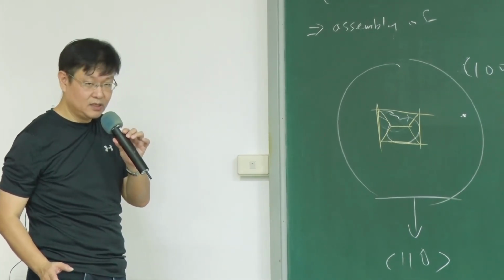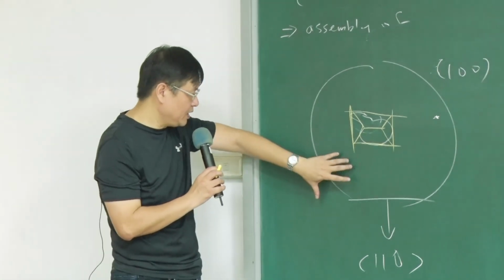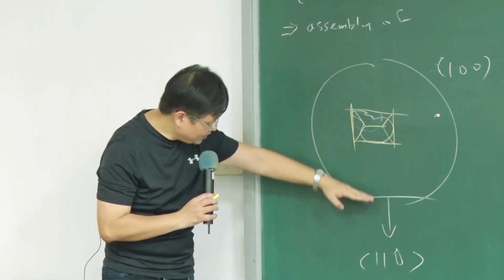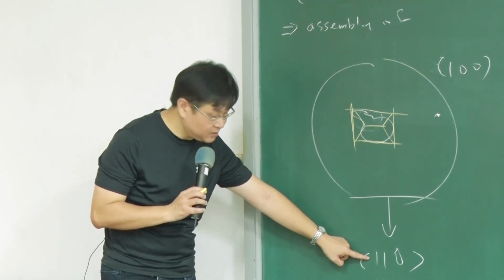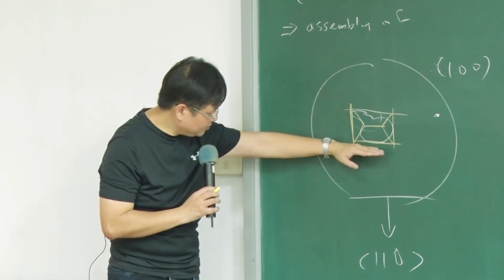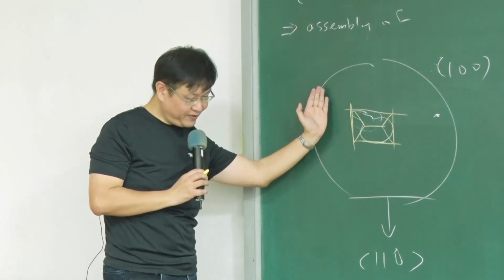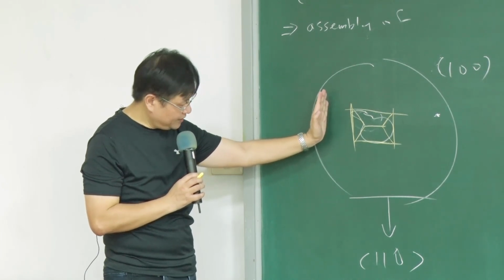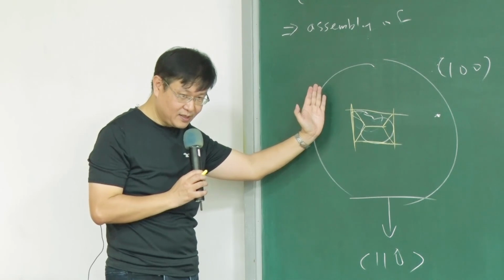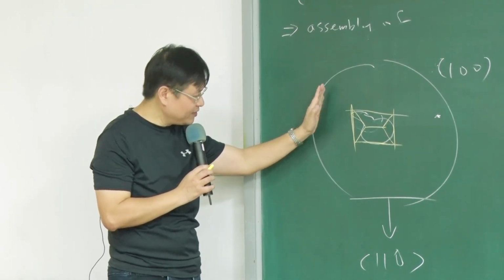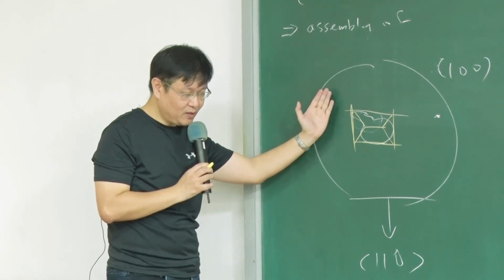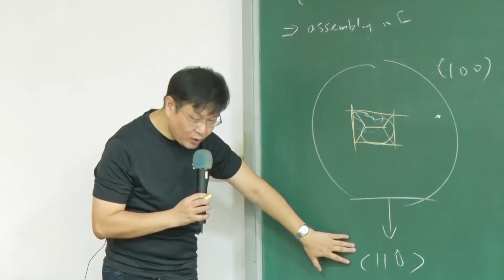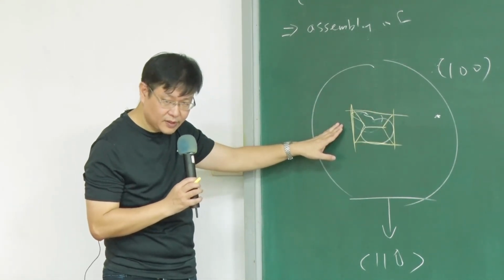No matter how you punch the hole, any kind of hole, you just need to draw 4 boundary lines first. The 4 boundary lines, remember, are parallel to the 110 surface. So this one is 110 as well, 110, 110, 110, 110. When they incline 55 degrees, you can find the 111 surface easily, right? From the 110 surface, you rotate 55 degrees. Sorry, not 55, it's 35 degrees actually. From this side, it's 35 degrees. You will end up finding the 111 plane. So first draw 4 110 lines. This is the final shape you can get.